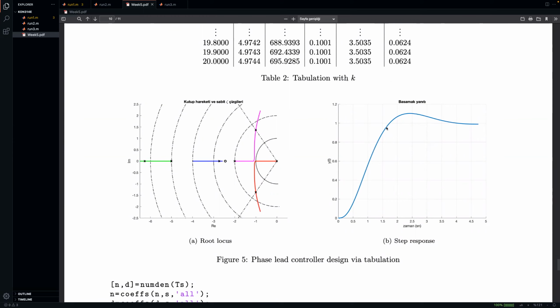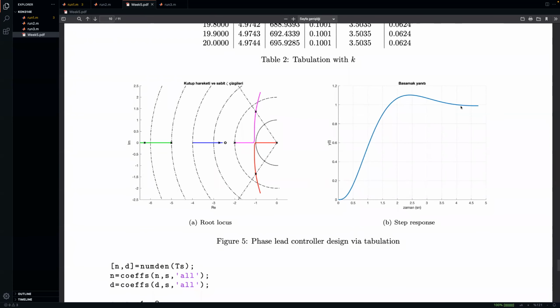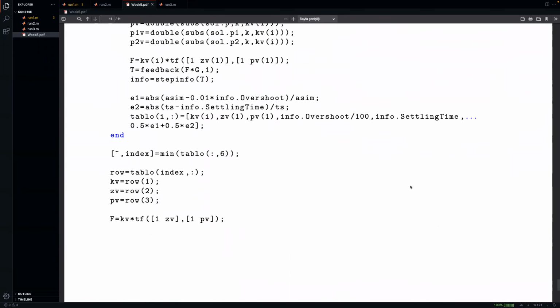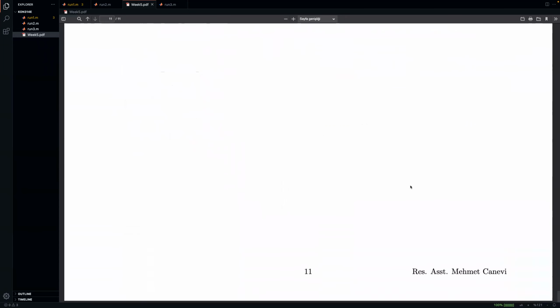So you can see it is basically possible to optimize a phase lead controller for this system, but again, in terms of root locus, it is possible to come up with a phase lead controller because of its angle contribution. We are basically looking for something that gets rid of the angle of S+5, so there would be a solution to that, and it would track the reference because it is already a type 1 system in the feed-forward path. So yeah.